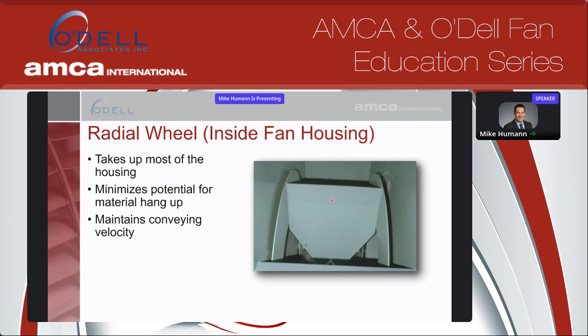recirculation. It also helps to maintain velocities coming in and out of the fan, so any material does not get stuck in the fan. And the last reason is to minimize any buildup or hang up with material between the wheel or in that dead space of the fan. So this is very common in radial fans. You'll see that the wheel takes up a majority of the housing width.